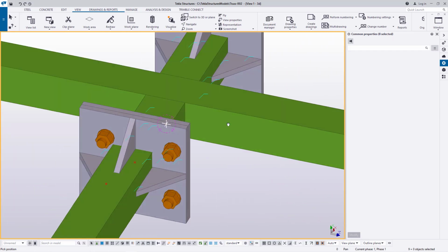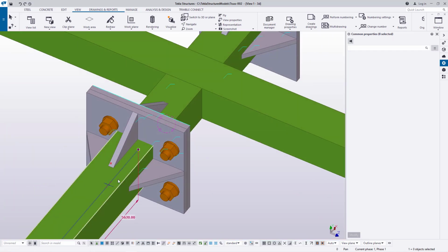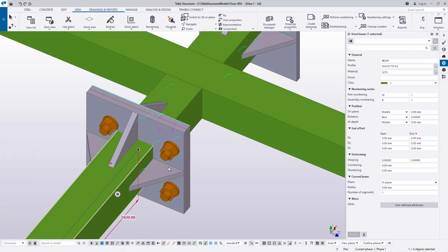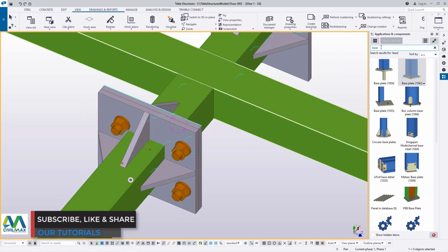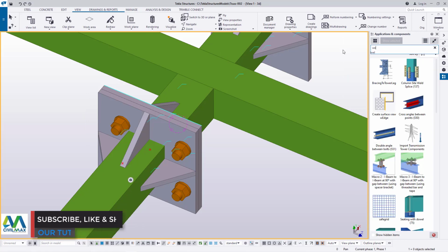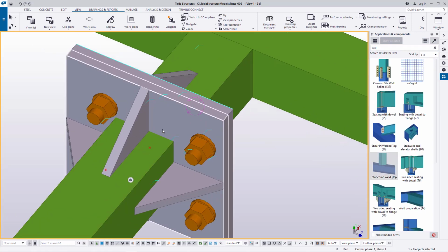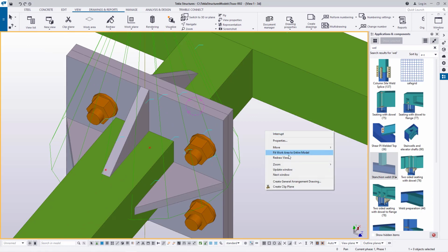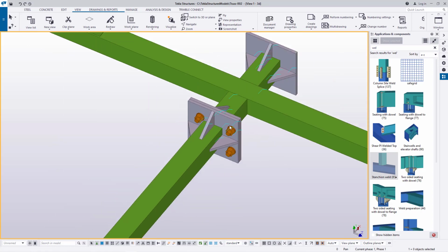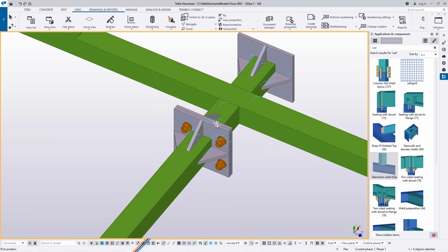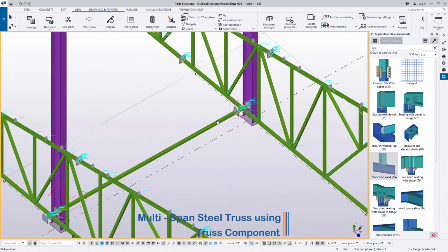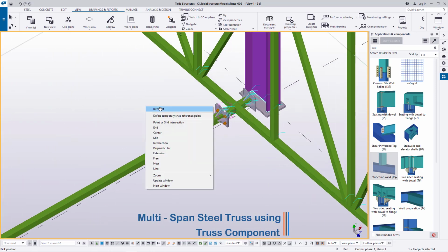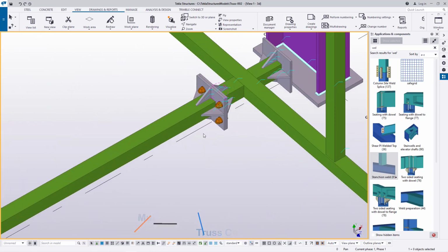So we have this one bolted, this far end, but if you take a look here, this plate is not welded to this plate. I'll pick on that spot and type weld here, and if I pick on weld, I'll be able to weld this plate to this member. So I'll right click and come to redraw, and you'll be able to see that we have our first tie beam in place.